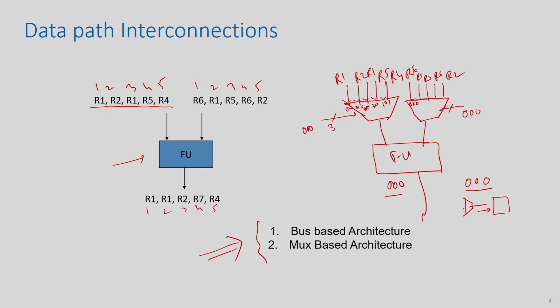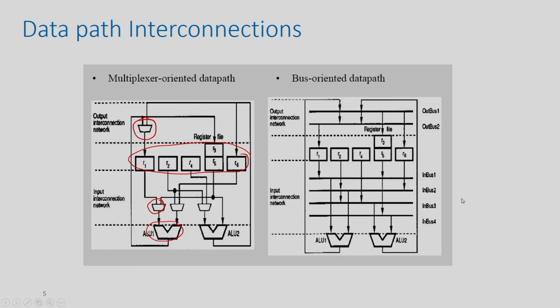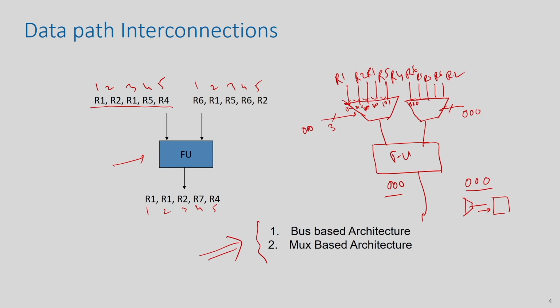You have multiplexers at the input of the FUs and at the input of the registers, because the register input can come from many FUs, and the input of the ALU can come from many registers. So you have to assign appropriate control signals, and make sure that the operation to be executed in that particular control step gets the corresponding control signal, then things will happen.